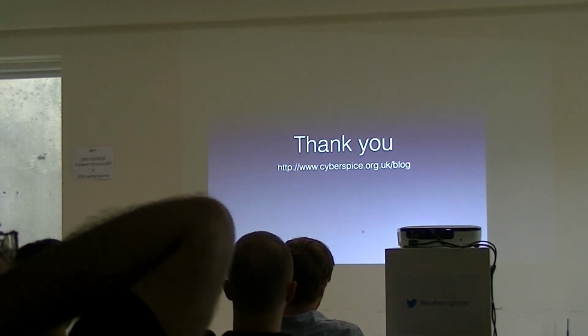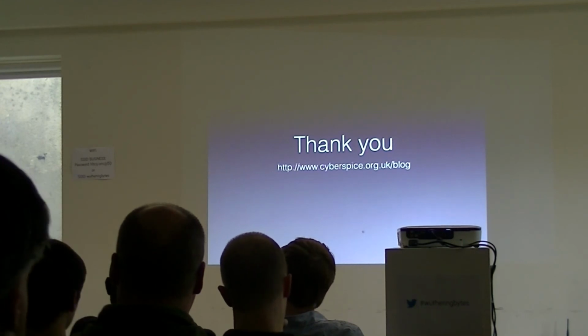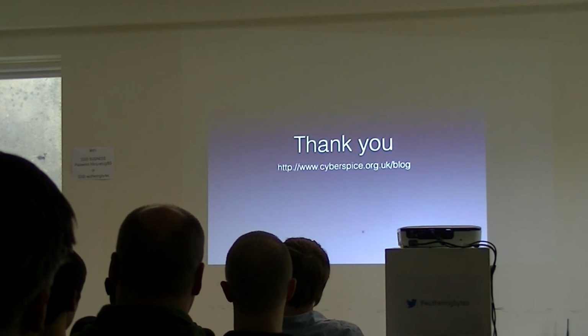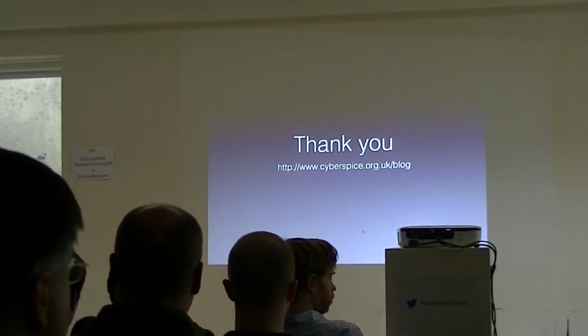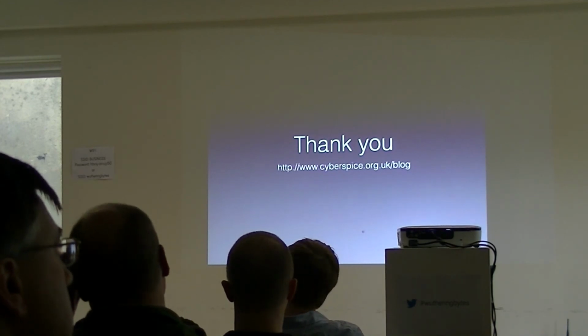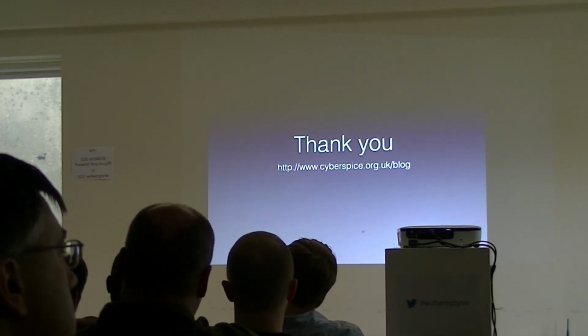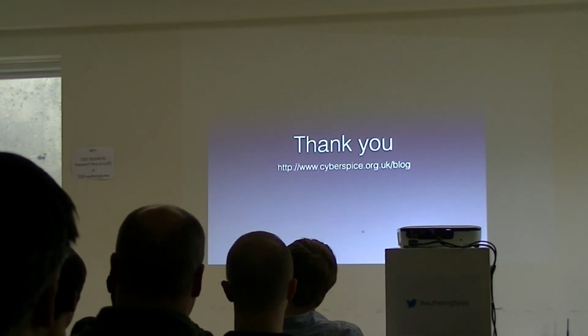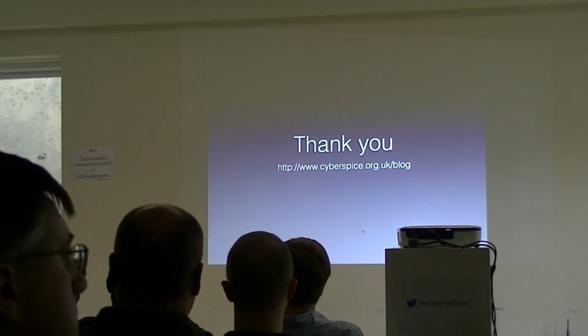So, for example, you actually have to write to a register of that chip to say which pins are outputs and which pins are inputs, and read from another register to read their values. So there's a little bit more work, but it depends on how confident you are with what you're wiring up.